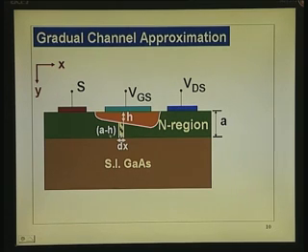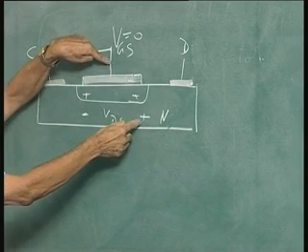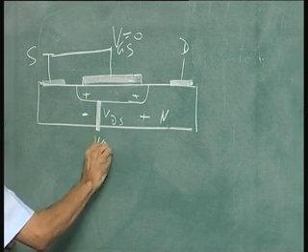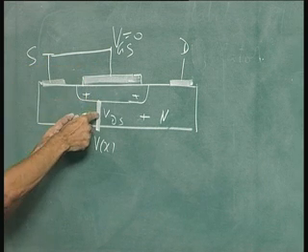It is just like taking a p-n junction and applying extra voltage across that. You are applying another plus minus across that; this is adding on to that. Let us put this example: you take a p-n junction, and you add on to the barrier potential if you reverse bias it. This is the potential; you connect it to that, it is as if you applied this voltage across that, additionally. So, built-in potential plus VDS comes in there. If you take any point here, if this is V of x, the potential drop here is equal to VBI plus V of x.